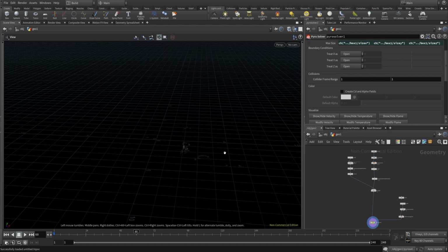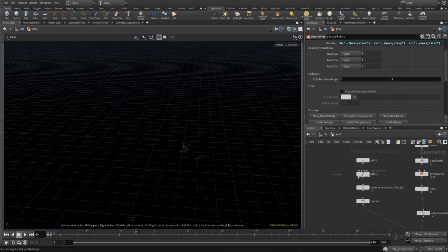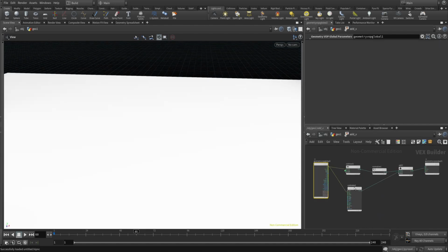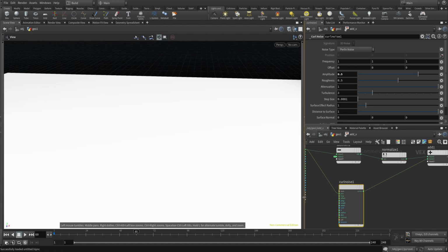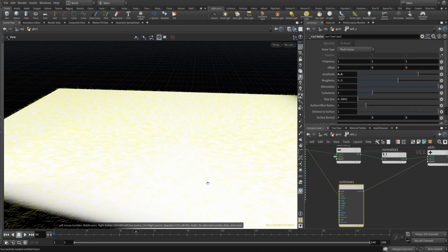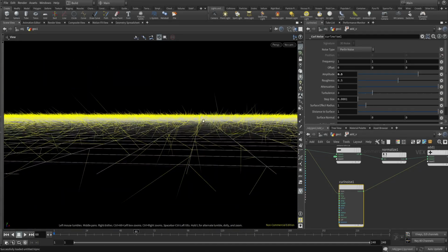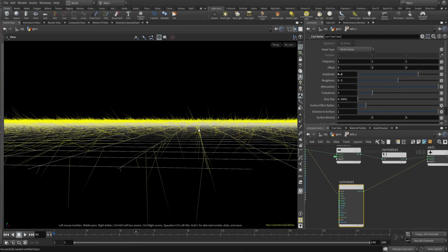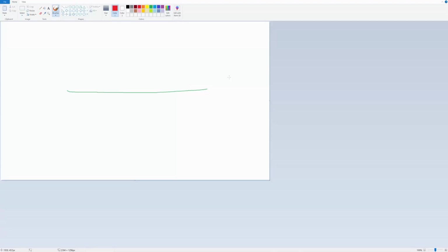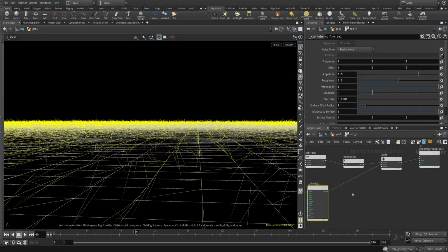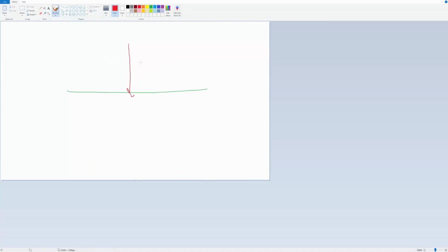If I want to have better motion of the shockwave, one thing I can do is playing with velocity data here. Currently, because of the curl noise, we have velocity vectors in both positive and negative y-axis, as you see. I want to do something to produce just velocity vectors toward the negative y-axis or downward. So at the beginning, my smoke should go down instead of going up, but because of the collision object which we have here, it's going up after hitting the collision object, and it's giving me a better result.